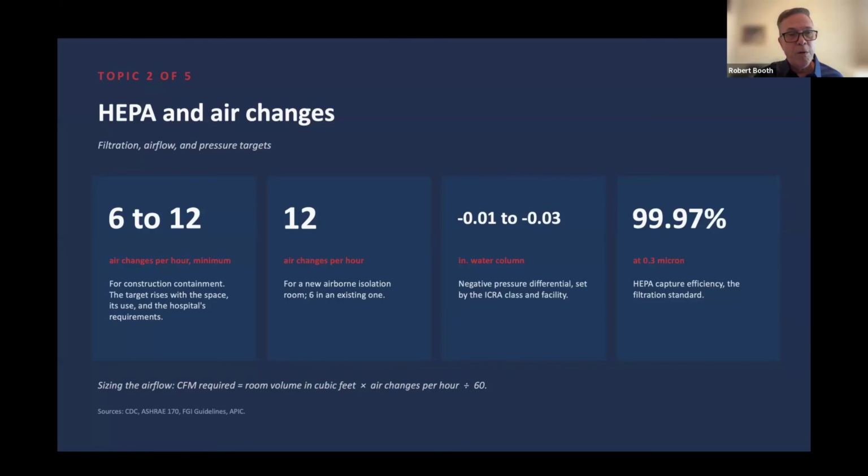filter and then record the pressure drop, which is usually about a half an inch. And then most manufacturers say another inch and a half, you want to change it. Because like Josh mentioned, HEPA filters get more efficient as they get loaded. We know that, but eventually they pass their life and they're not able to give you that CFM. This is one reason we don't put HEPA filters in supply diffusers, because you get a big pressure drop in CFM. So it's not efficient to do that. We do it back at the air handler where we can do it.